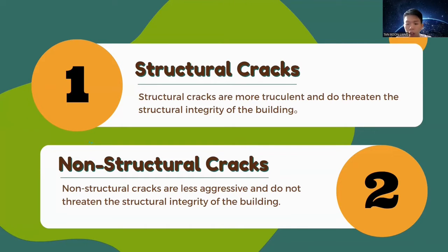They are often caused by incorrect design, poor construction, shallow soil, chemical reaction of the construction materials, overloading, and differential settlement. They are typically accompanied by problems like sticking doors or windows, slanted doors, and sloping floors.